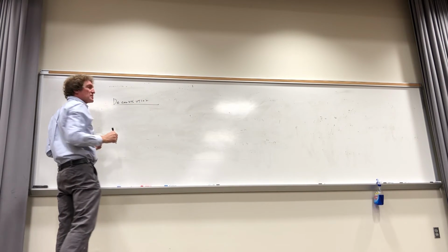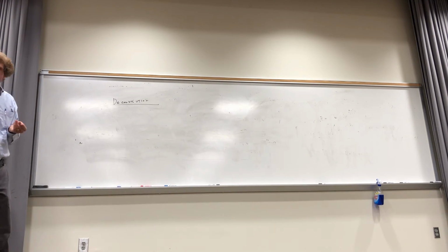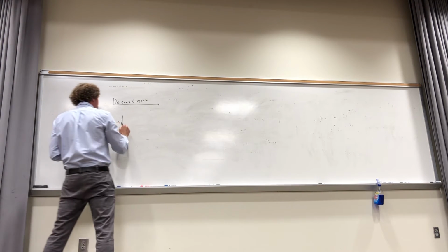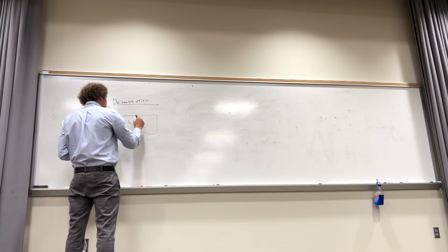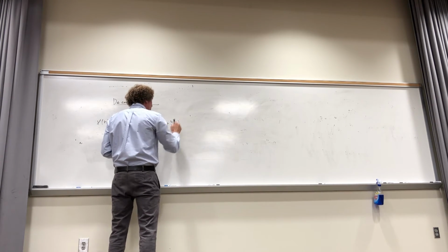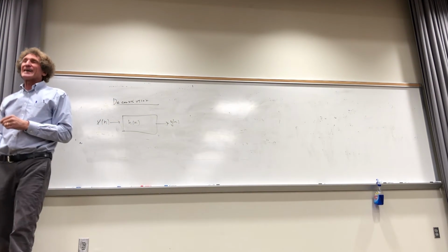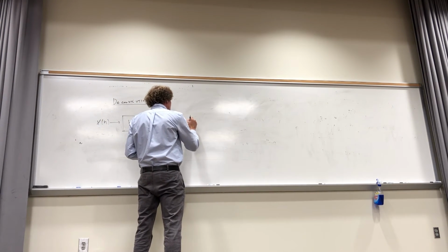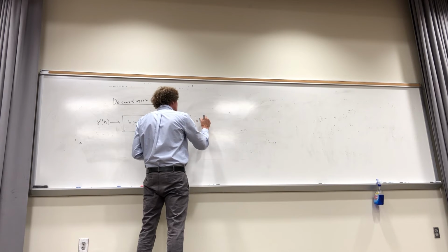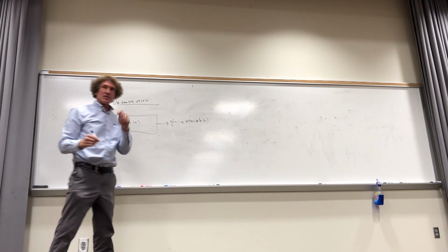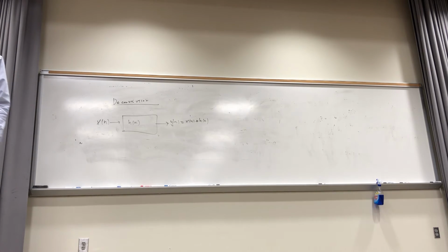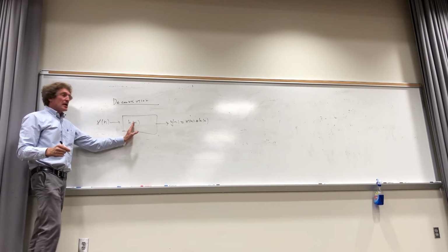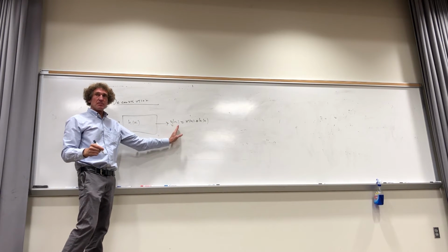Now, in his book, he talks a little bit about deconvolution. Here's what it means. Normally you have x of n, and it comes into something that has a response h of n, and you get a y of n, right? Y of n would be the convolution of x of n with h of n, or vice versa, h of n convolved with x of n. What this can represent is a sensor, and here you're reading the output of the sensor.